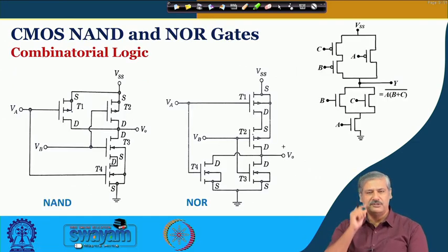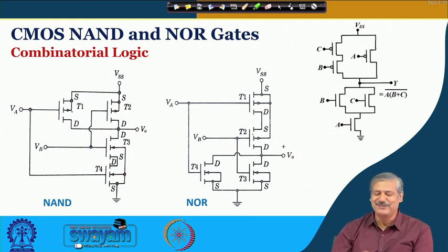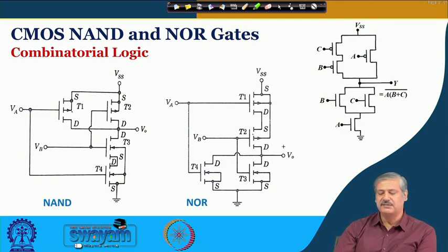Fine. So, this is one beautiful thing about these MOS based gates. Okay. So, when we look at development of NAND gate or NOR gate or combinatorial logic, we do not need resistive elements and other things that was there in BJT based circuit development. So, in NAND gate development in CMOS, we need for every NMOS another corresponding PMOS, okay, to get the advantage of the CMOS circuitry.